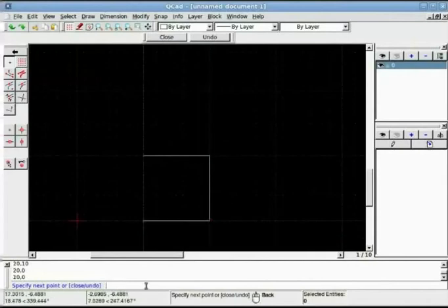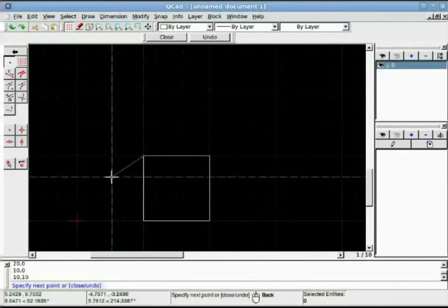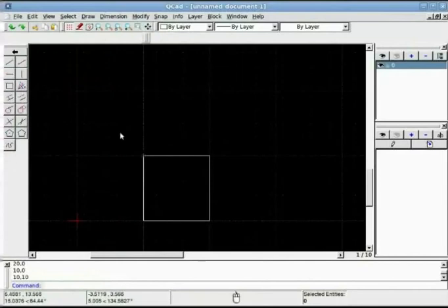Now to close my drawing I can simply put C and enter, or I can go back to my original point, which was 10, 10, and it will close the drawing. This is how you draw using command line input. Now you can draw any drawing using this coordinate system by adding and subtracting absolute coordinates for any point or vertex between two segments, like I did to draw a 10 unit distance for this drawing.